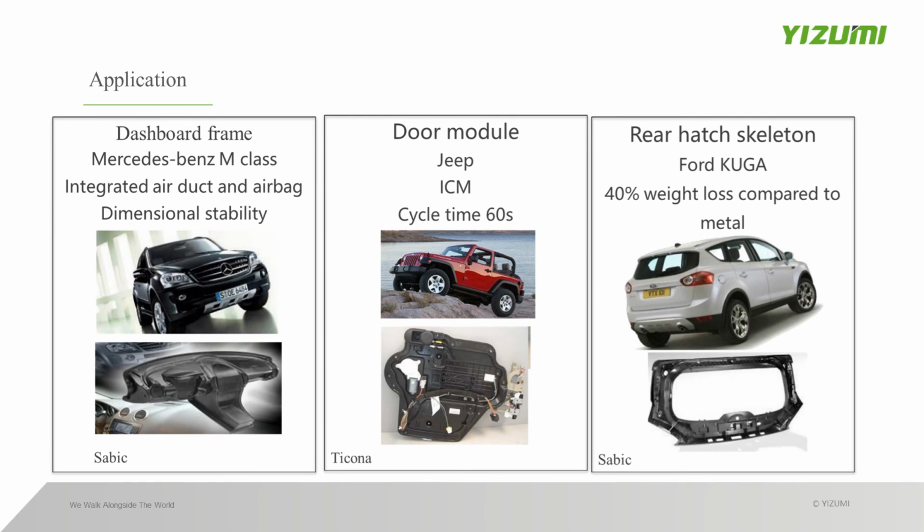In China we always use metal parts, not plastic parts. But foreign makers such as Nissan and BMW have gradually adopted long glass fiber plastic for rear tailgate technology, because the plastic can include two parts, outer panel and inner panel. They use 30% to 40% long glass fiber reinforced plastic and use adhesion technology between the two parts to ensure the structure and appearance requirements.